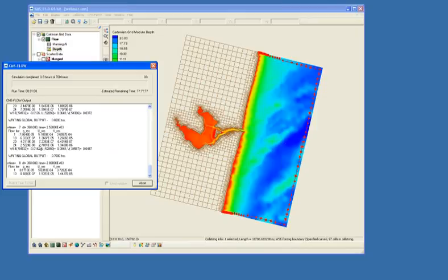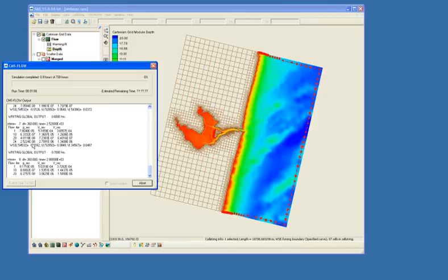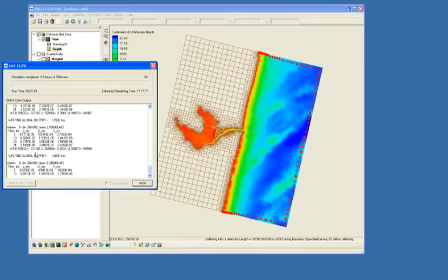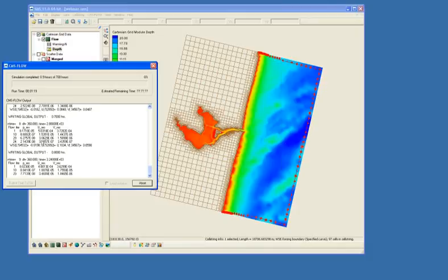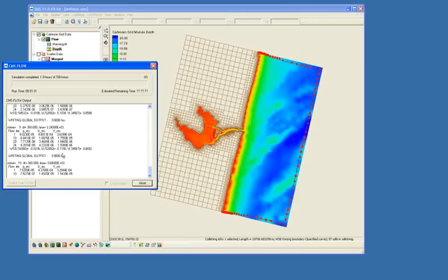And if it gets to 40 and it still has not converged, this exponent right here might be very small, like e to the minus 4 or 3. You want to make sure that these final iteration values are very, very small numbers. So that's one thing to look at.